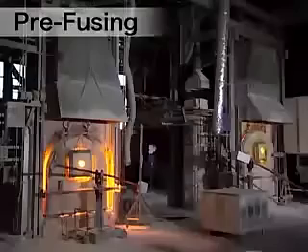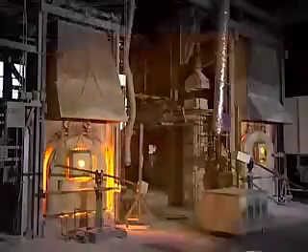Impurities such as iron that cause reduced transmittance are removed to the order of parts per million, and each material is precisely measured and placed into the V-shaped mixer. The blended primary raw materials are placed into a platinum or quartz crucible and fused in a furnace under strict temperature and time control.